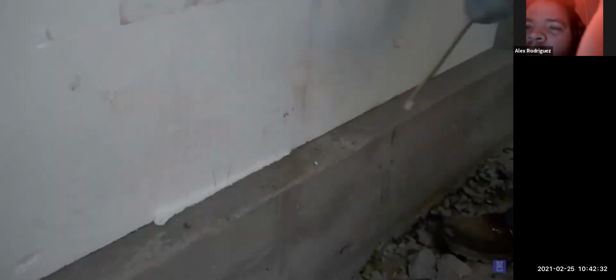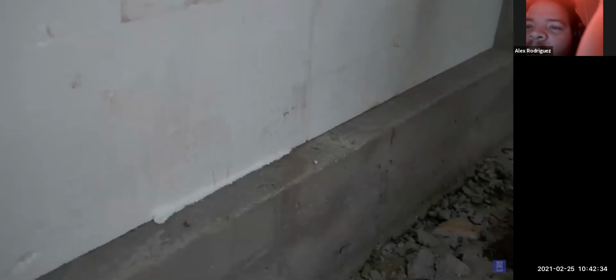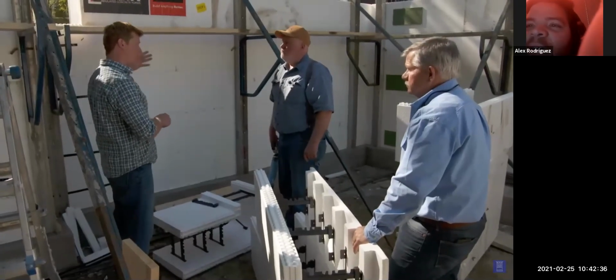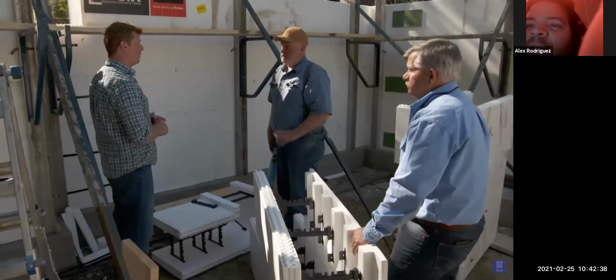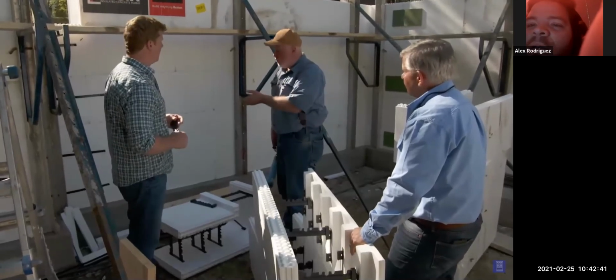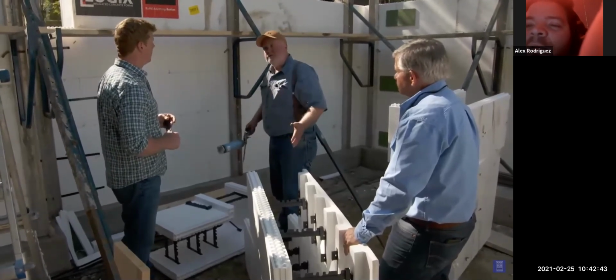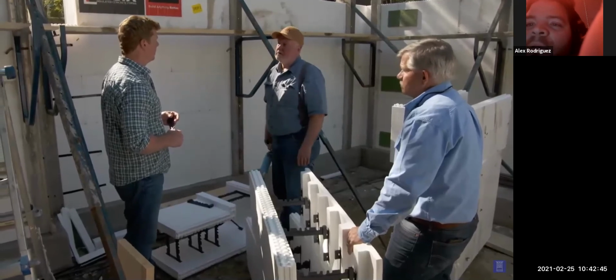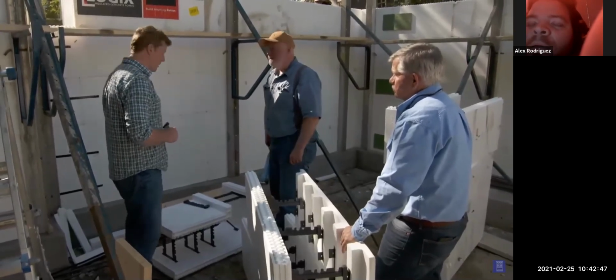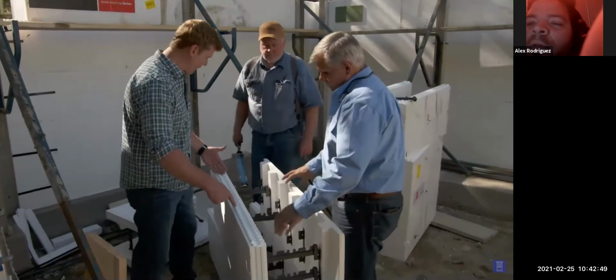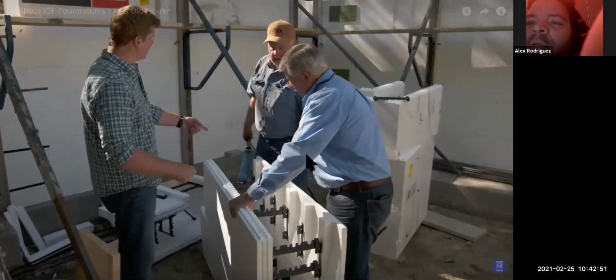That's all it takes, huh? That's all it takes. That's not actually stopping us from shifting or kicking when the weight's in there. That's just to hold it in place so your plumb was set up. That's correct. We don't want them to move, and they don't want to move. They don't want to shift around on the footing. So that gets us to the footing, and then when you attach one form panel to another one, are you using adhesive for that as well?